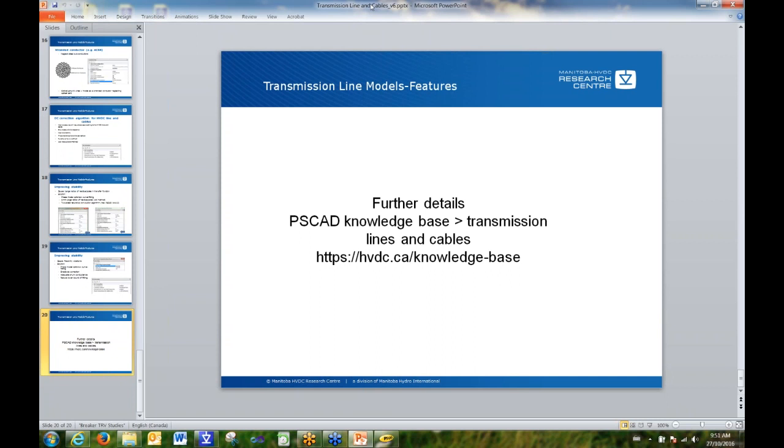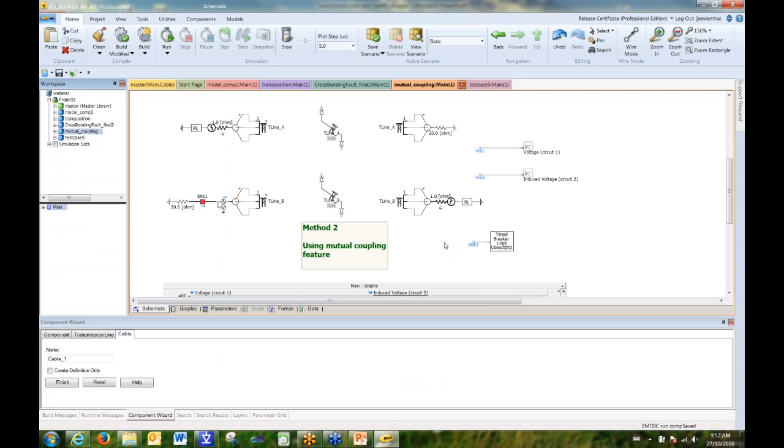So there are a few questions. When do you use long line corrected values? I think it's for load flow studies. You may need those values to analyze the transmission line. So that's where you need the long line corrected values. Those are the RLC values for the entire transmission line.